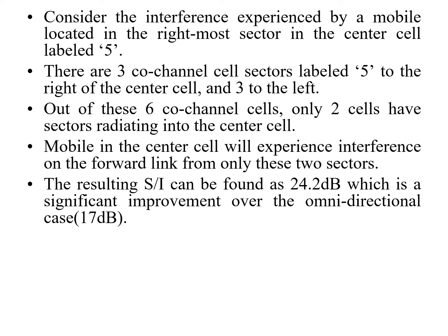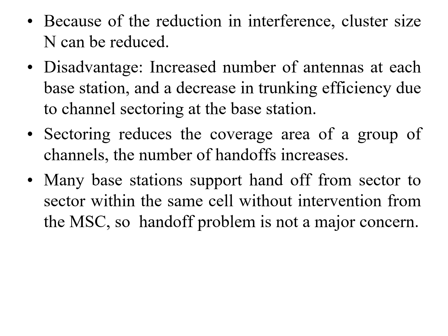The resulting S by I ratio can be found out as 24.2 dB, which is a significant improvement over the omnidirectional case of 17 dB. Because of the reduction in interference, cluster size N can be reduced.